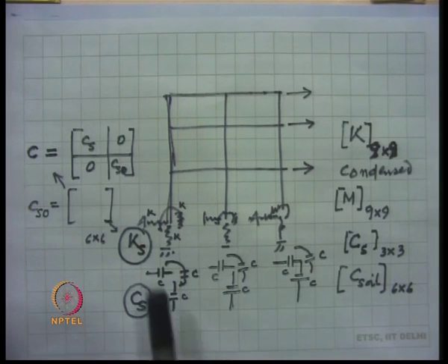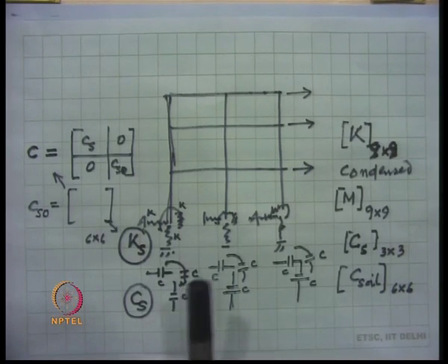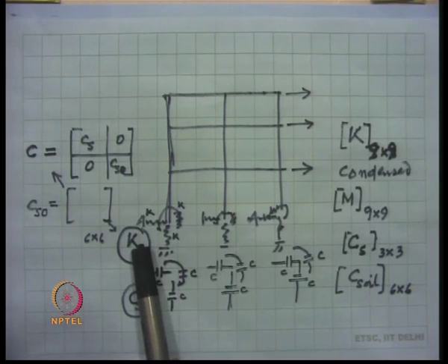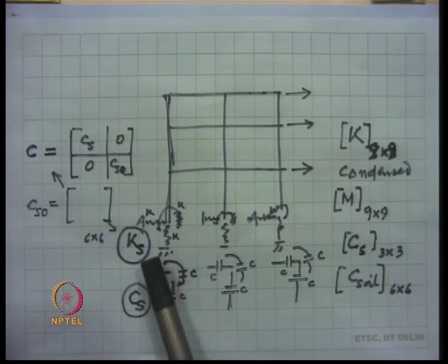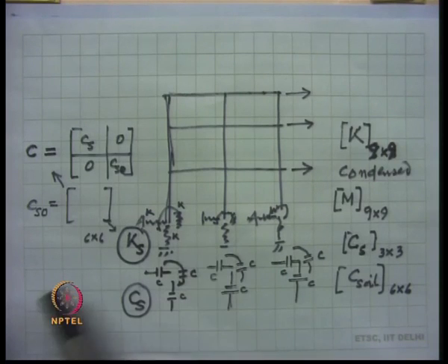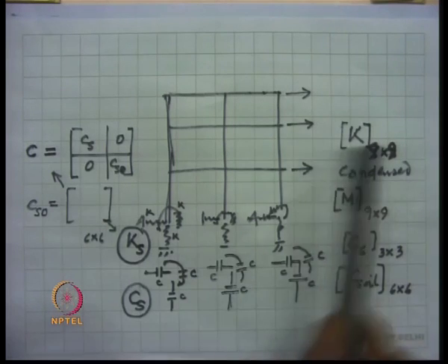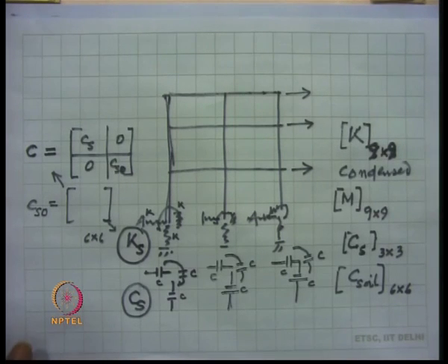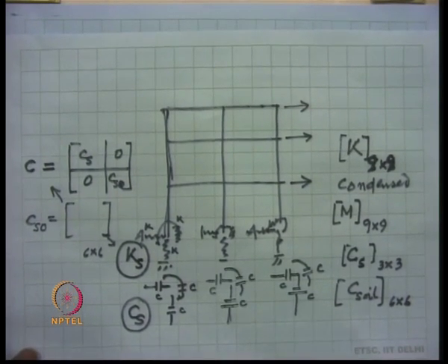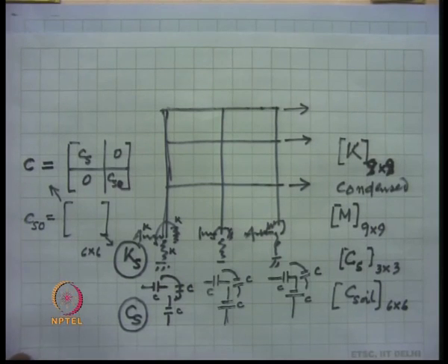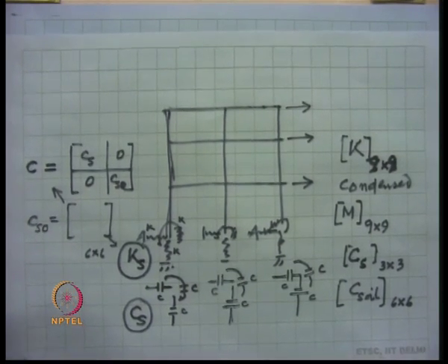Note that while performing the response spectrum method of analysis, we retain these springs at the bases, that is these lateral springs and the rotational springs. They are retained, and then we perform the static analysis corresponding to each mode of vibration with its equivalent static lateral load.